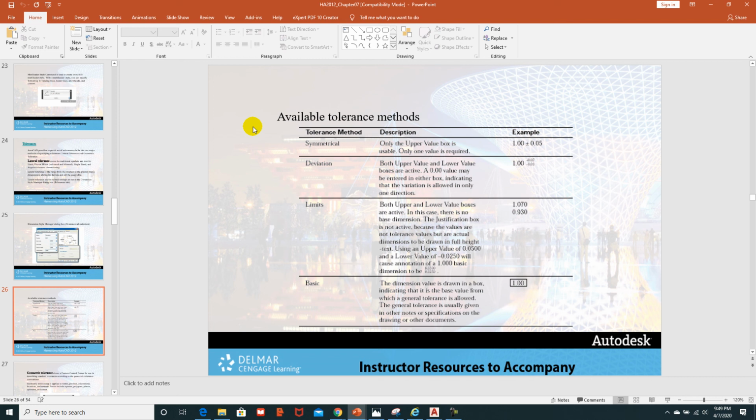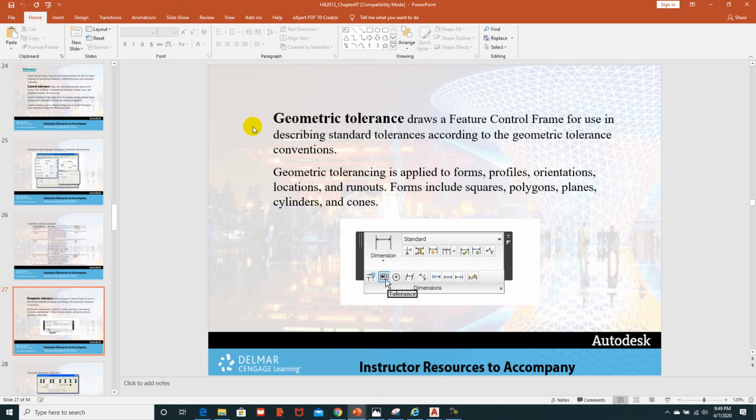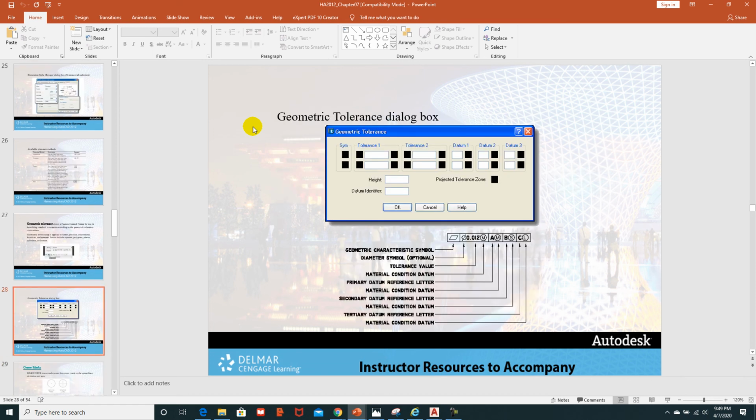If you need something precise, but it doesn't have to be exact, then you have a deviation. Plus 0.002, minus 0.003. Plus a piece of paper or minus a piece of paper thickness as I build that. And that's kind of how it really works, because nothing is perfect like it is in the computer. When you get out, you have things like temperature, you have materials, and that's where GD&T, or geometric dimensioning and tolerancing, comes in, where they'll give even more standards and control points for the size of these parts. And all of your aerospace companies and high precision manufacturers will use GD&T.